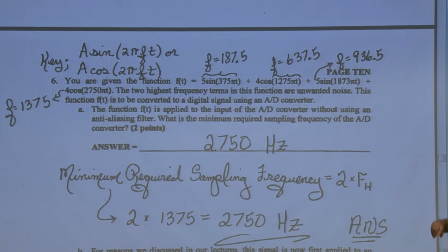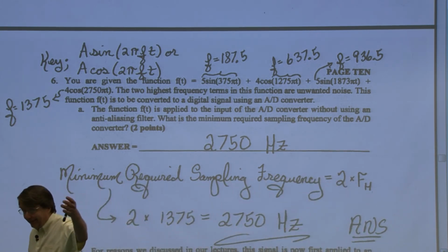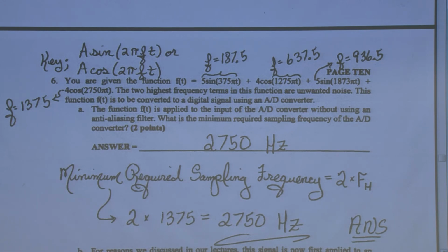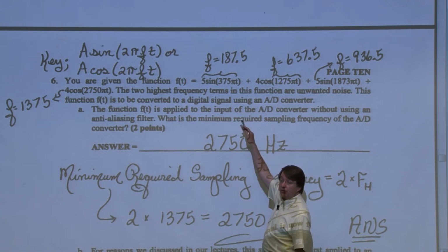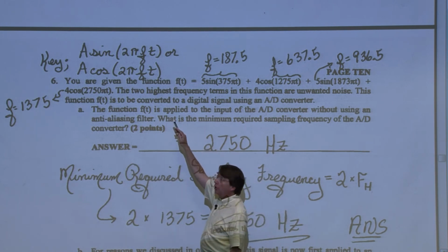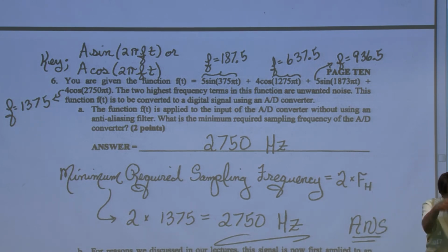All right. Now, just to make sure you don't make a mistake, I mean, this is very basic. I know you know it, but sometimes we forget the most basic things. The standard way of writing a sine or a cosine inside the argument is 2 pi ft, or omega t, where omega is 2 pi f. So if I write it as sine of 375 pi t, that means 375 pi t equals 2 pi ft. So notice the frequency is not 375, it's half because of that 2. Just be careful, that would change the whole problem. Okay? So now we get the 4 frequencies.